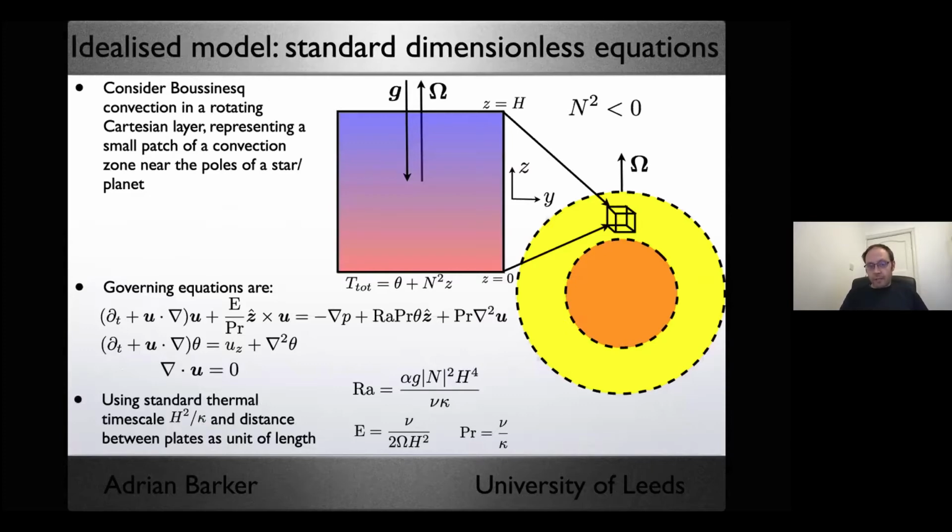The setup that I'm going to use is a standard model to study convection, the Rayleigh-Bénard setup. That's a setup where we have convection driven between a hot plate at the bottom and a cool plate at the top, separated by a distance, referred to as H here. In this setup, the static conduction profile, where the heat is just transported through thermal conduction, gives you this linear profile in z.